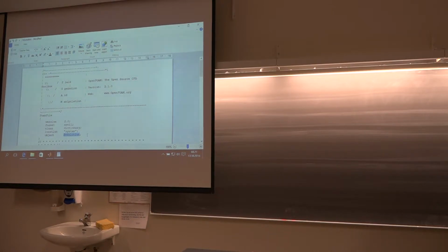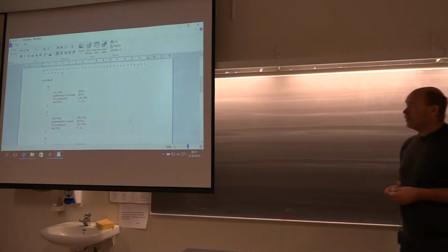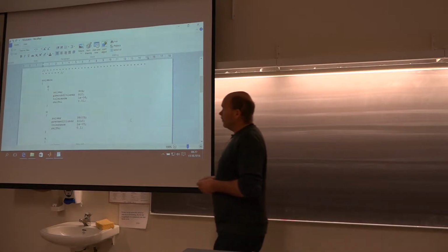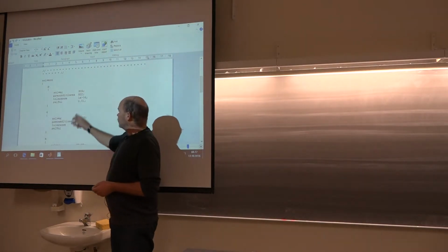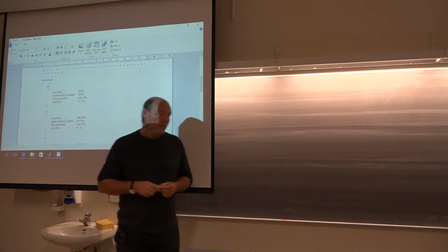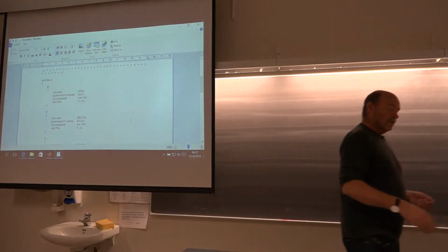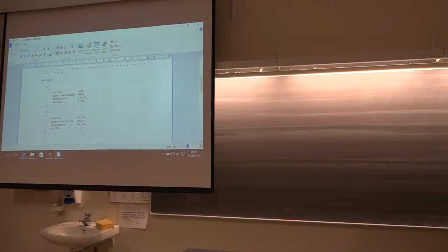And here we have a lot of choices to be made, a lot of input. We have some strange names, PCG, BiCG, sometimes it will be an MG or whatever. And here we have to specify which solver should be used to solve the algebraic equation system.